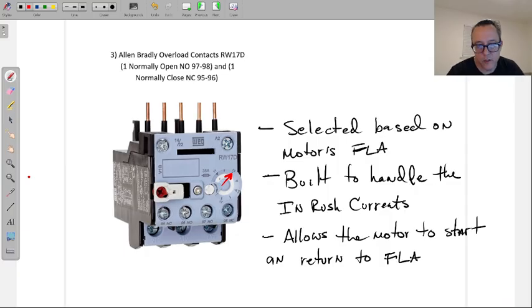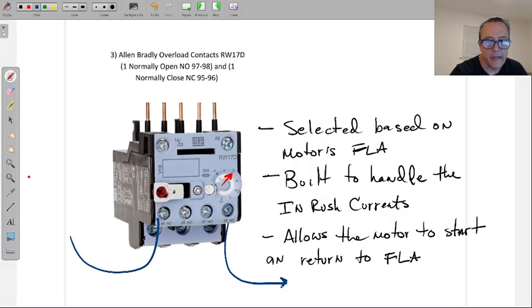All right, just like a breaker, it trips. And so I run the neutral wire, and you guys have already done this, to the normally closed contact and out of the normally closed contact to the A2 side of the coil. Inside this little thing in here is a normally closed set of contacts that is always providing the neutral or the negative to the A2 side. And as long as there's no problem on the motor, your neutral will always be there.